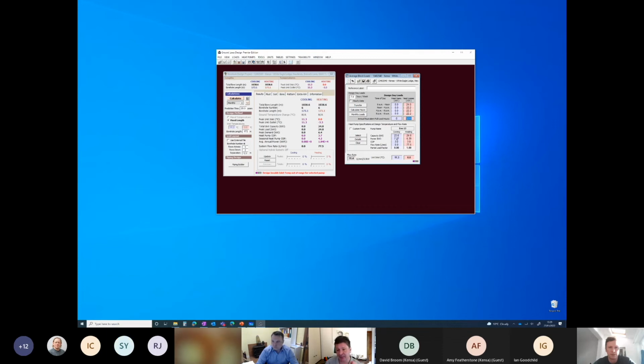We then select a heat pump, and in the background of GLD, there is a 3-dimensional map of heat pump performance. If you imagine the horizontal axis is load temperature, the other horizontal axis is the source temperature. The vertical axis, there's 2 of them actually. One is how much power the thing's consuming, and the other is the thermal output of it. So as we go up in temperature in a heating system, we lose both output and we consume more electricity. And we can cover how efficiency in heat pumps works.